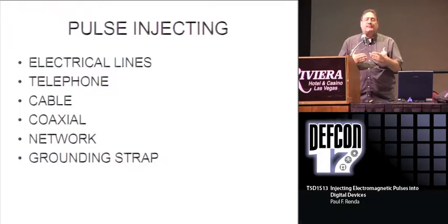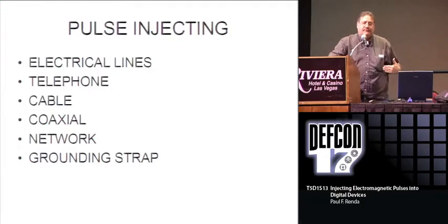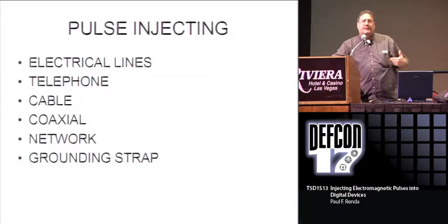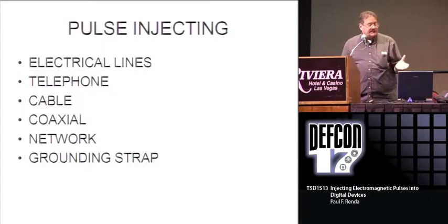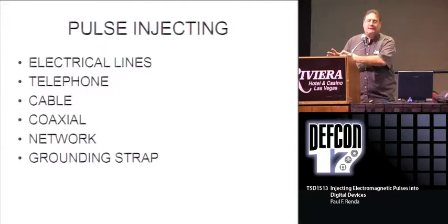In free air, the pulse drops off as 1 over R squared. If I'm 1 foot away from the spark gap, and then I move 2 feet away from the spark gap, it drops off by 1 over 2 squared. In other words, at 2 feet, the value is 1/4 as high. If you inject electrical wiring, which could be any of these wiring here, it basically becomes an LCR circuit, an inductance, capacitance, resistance equivalent. But it travels for many, many meters, many, many hundreds of meters.